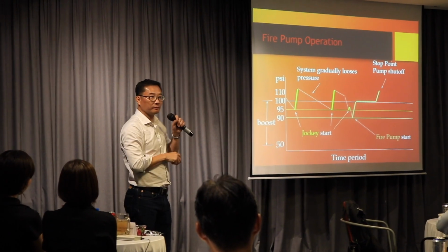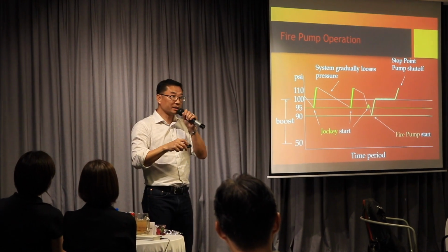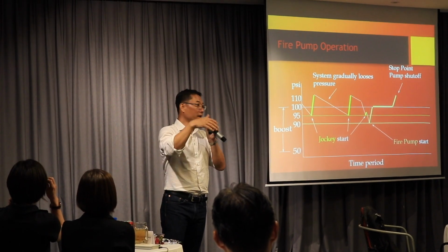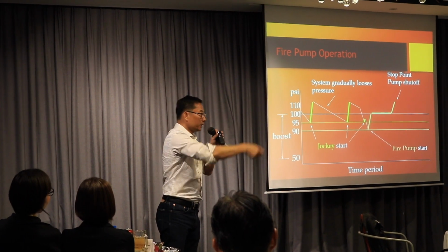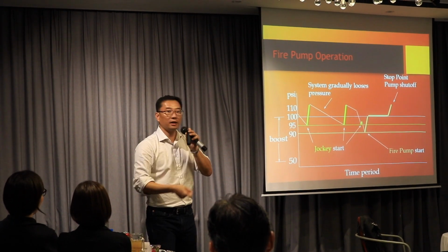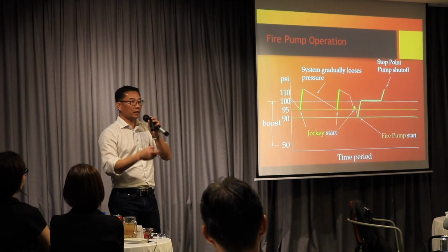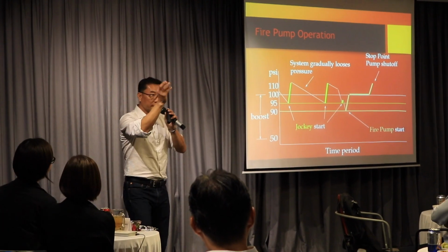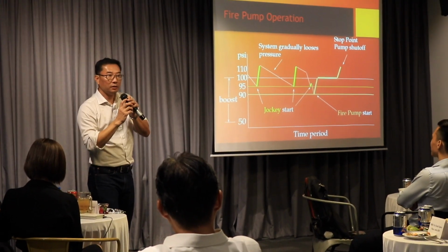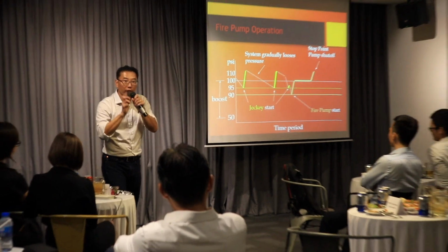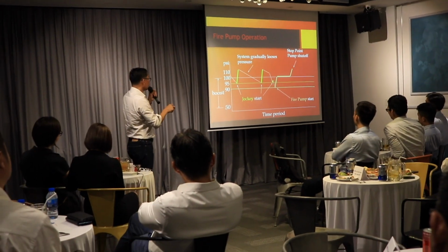5%. The main pump start may not be needed. You remember I told you, maybe a fitting is loose and the water is leaking, maybe someone at the hose reel turned it on to wash a car or take some water for cooking, I do not know. Or some fitting or valve is a bit loose and the water leaks. You do not want to start the pump because there's no fire. So what? The jockey starts.